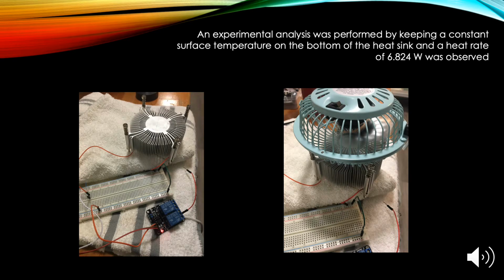I wanted to experimentally analyze the heat sink by calculating the amount of energy generated required to keep this fin at steady state under the convection conditions. I did this by using an Arduino to set a constant temperature boundary at the base. I then went through and insulated the backing of the heat sink so that essentially all the heat generated would travel through the sink rather than out the back of it.